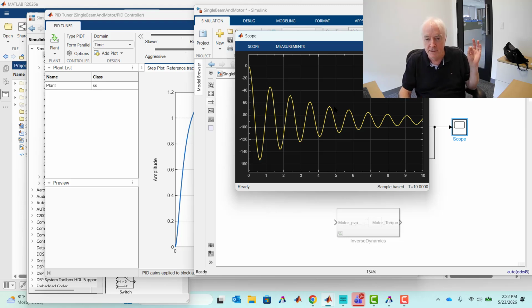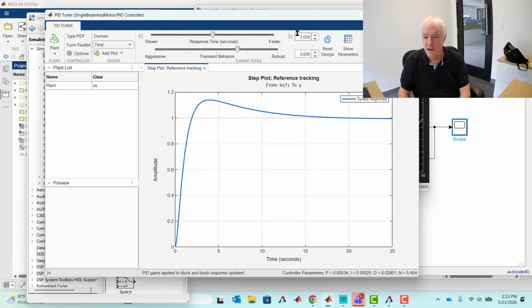just point out that the linear control approach is based on one data point with regard to time, and that's t equals 0. It's called the operating point, about which a linearization takes place. And certainly, even the simplest of mechanical problems typically are not linear. Right? That's an issue that we're contending with right now too. But I'd still say we can get there, right? And that the method is still used so well because these things really do work.